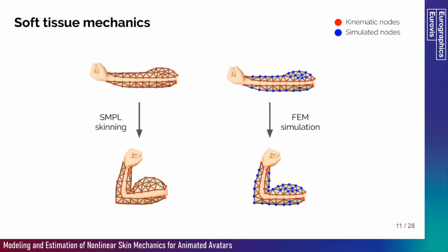At this point, we can make an important observation. The external surface of the FEM avatar is exclusively determined by the simulation, not by the SMPL model. For a static avatar pose, surface nodes tend to the less deformed configuration, minimizing the total elastic energy. As a consequence, the surface of the simulated avatar usually does not coincide with the surface of SMPL. One can assume that a mechanical parameter estimation can help us reproduce the realistic SMPL surface deformations. However, due to the complexity of the original human anatomy, matching exactly the data-driven model is an extremely and perhaps unsolvable problem.